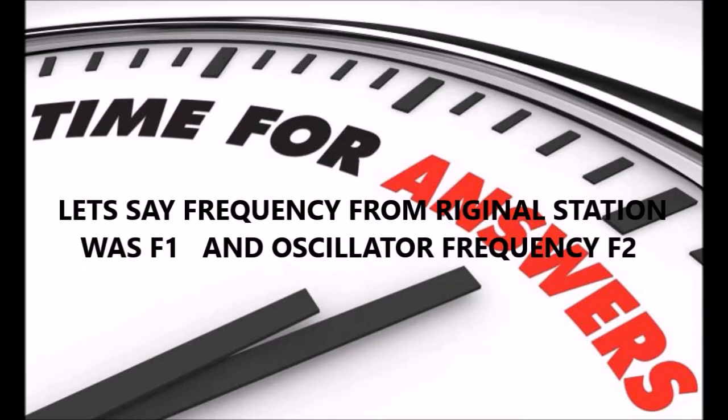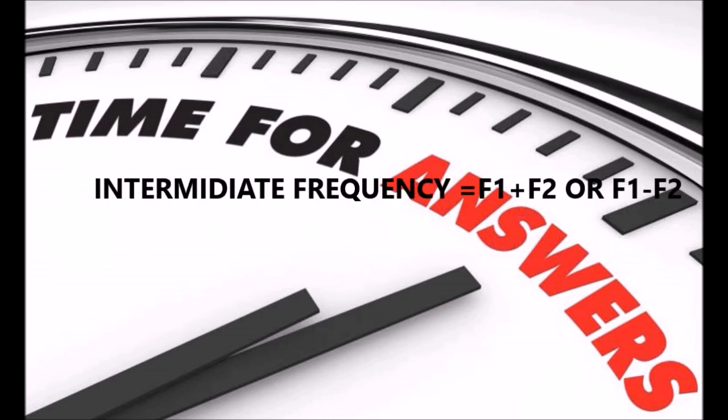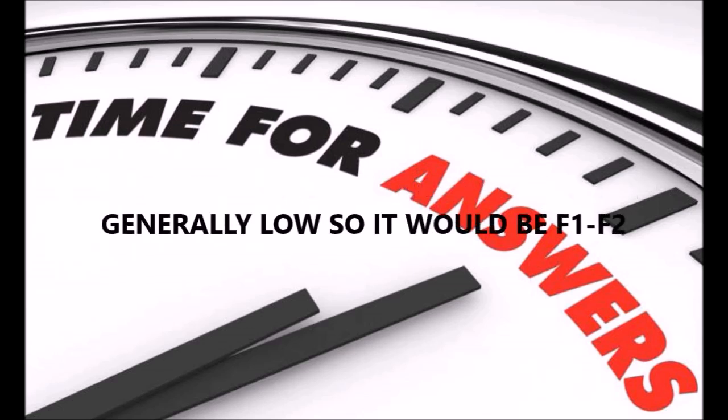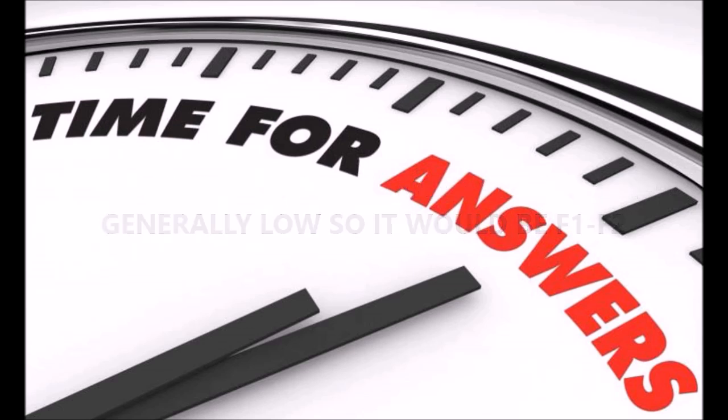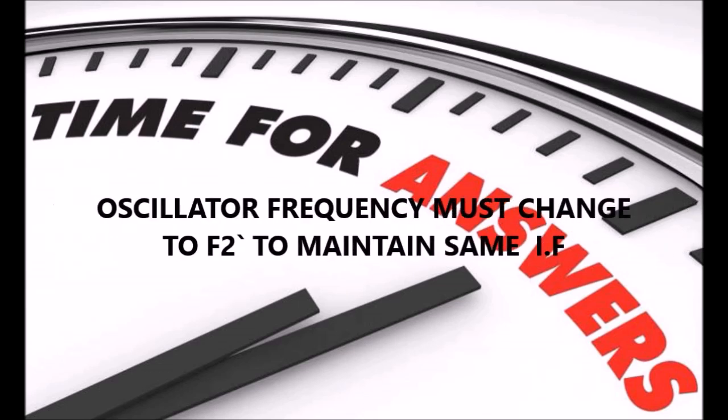Let's say the original station frequency was F1 and the oscillator frequency obtained from LO was F2. Then the intermediate frequency IF is equal to F1 plus F2 or F1 minus F2. It is generally low, so it will be F1 minus F2. Now, if the station is changed to a new frequency F1 dash, then the oscillator frequency must also change to F2 dash to maintain the same IF.